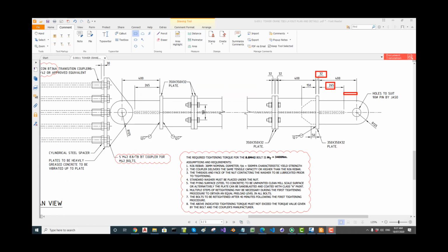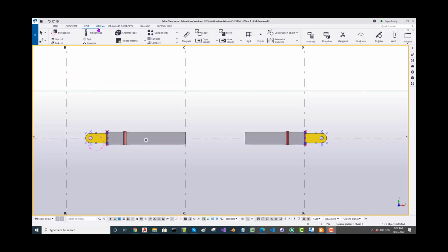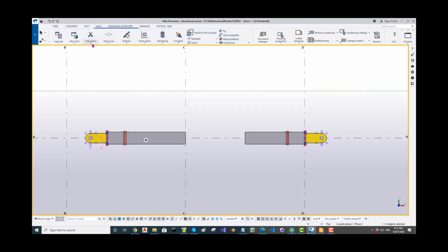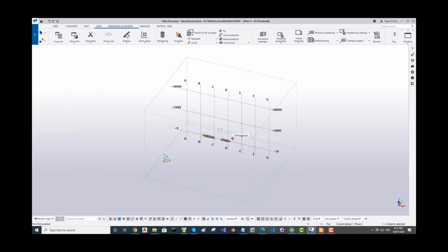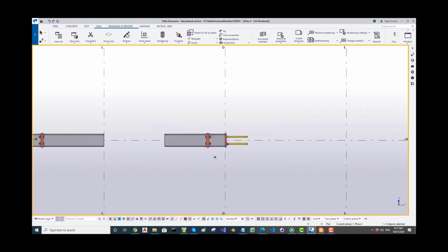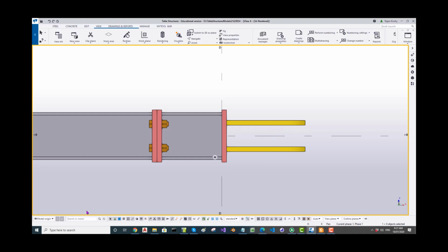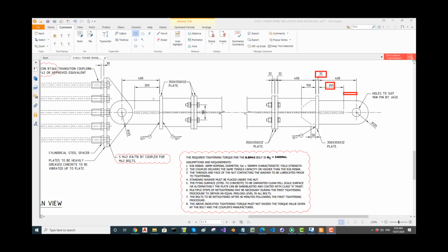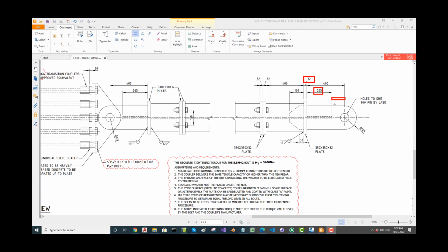That stiffener is in the mid plane, so I necessarily have to open a new view on this plane. So let me open a new view on that plane. So going to view, new view using 2 points, and I'm going to click these 2 points, and here is the new view. Okay, now we want to add a stiffener there. Okay, it's a 265 here and 265 here, same length, so that's fine.